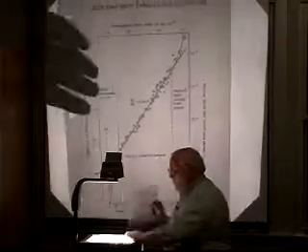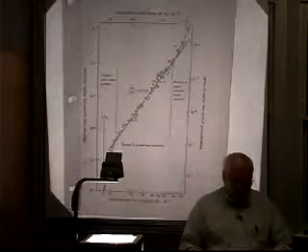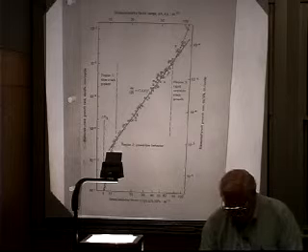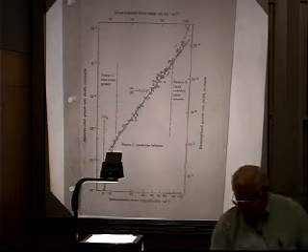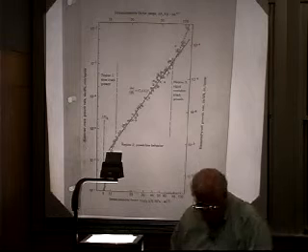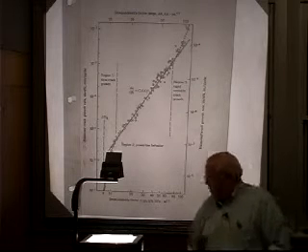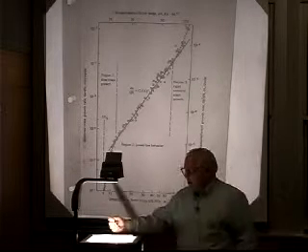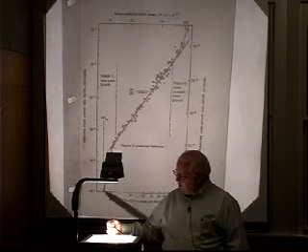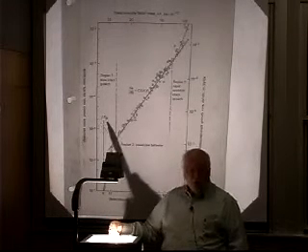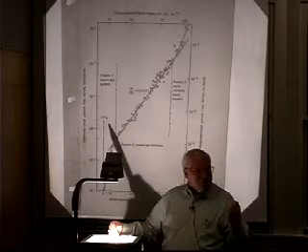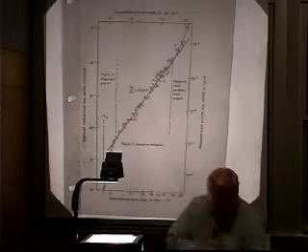What happens now is this is based on fracture mechanics, and I can do it under one type of stress, and I can calculate what it would be under another type of stress, because I have the science of fracture mechanics as the basis for my extrapolation. So down here is small crack growth. There is a limit. As this thing starts to approach, there's delta K threshold. That's the fatigue limit that the other people used to talk about in the old business.